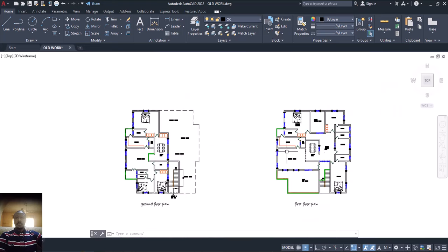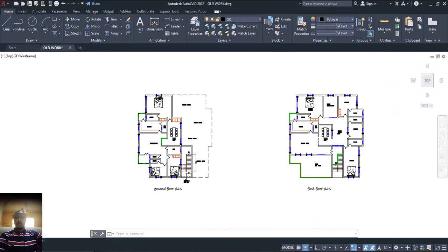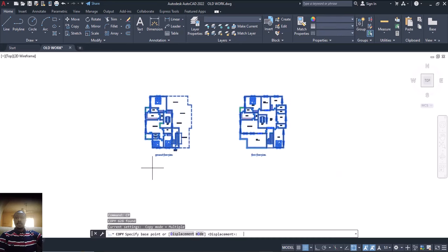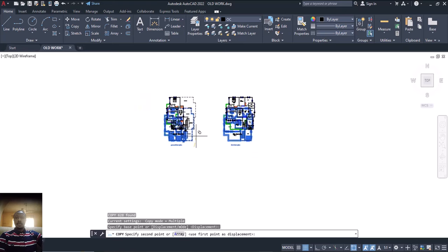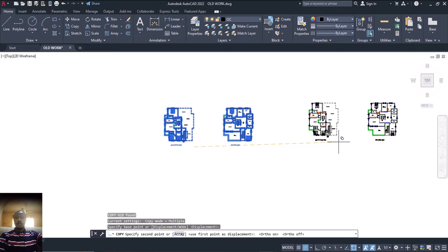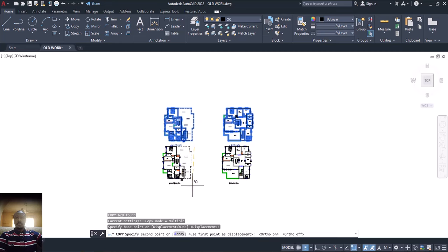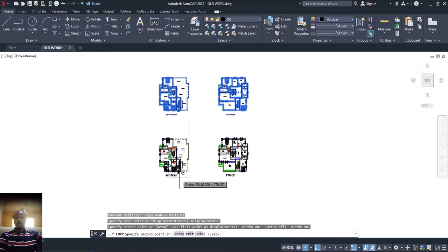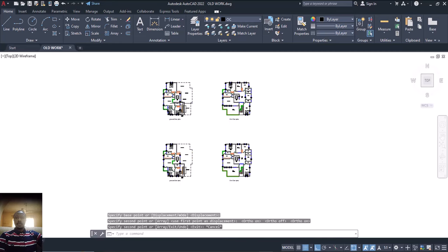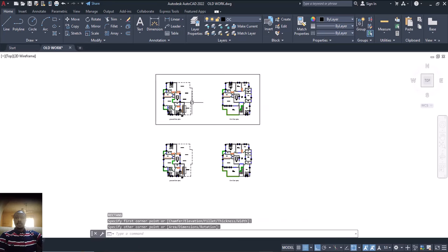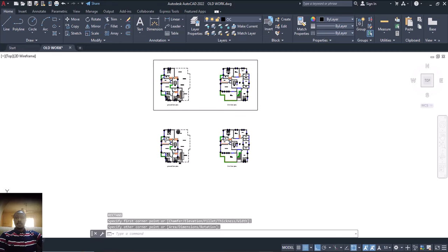All right, so let's start our GA. For us to start, the first thing I'm going to be doing is I'll first of all copy this. Then CP, enter, copy. CP stands for copy, or CO means copy. All right. For you, you might decide to put it on this side or up or left. For me, I always love it to be down here. I prefer it down here. All right, straight. Okay, so now this is my original document. I'll press my rectangle, that's REC, then enter. This means this is the original document. All right, so this is what I'm working on.